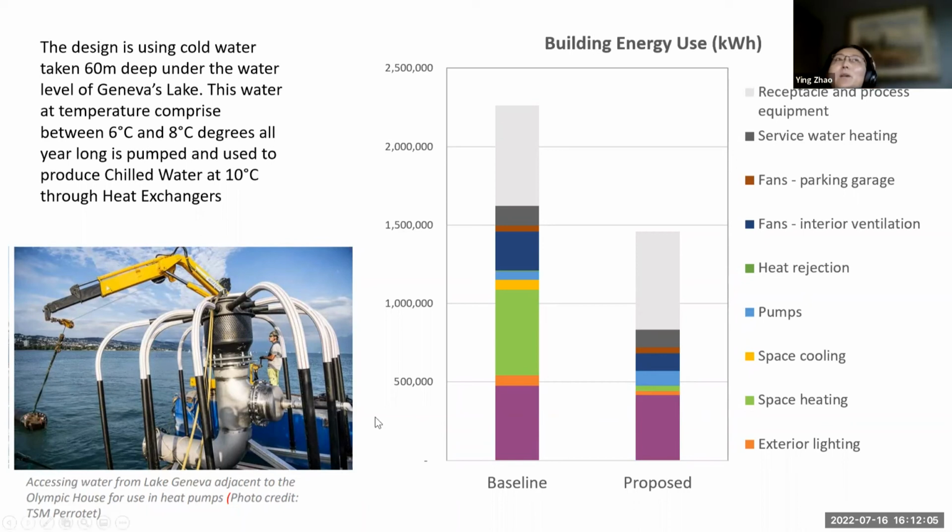The baseline is based on the LEED required baseline, which is ASHRAE standard. For this version, they require daylight controls and occupancy sensor controls in most of the space. If they are available, for example, if you have a big space with windows, that baseline requires daylight control. So for this building, with daylight control, they won't get much savings from the baseline for those controls.